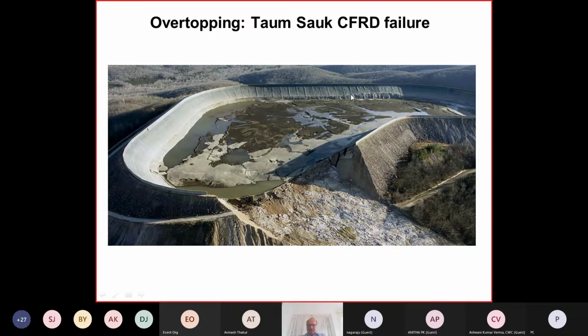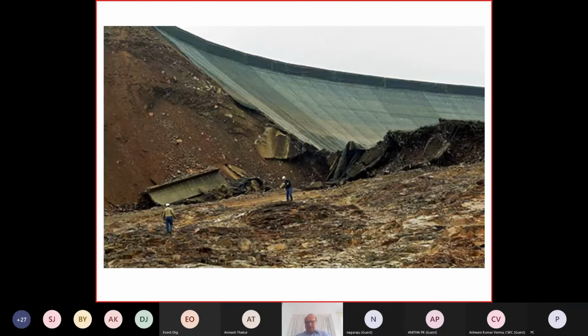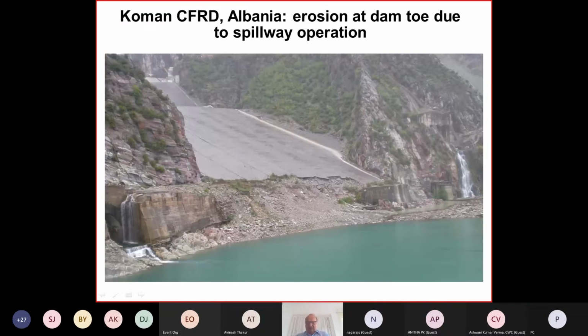So even if you are on top of a hill with no inflow, as part of pump storage, you must have a spillway. Okay, it is that simple. We see here some parts of its concrete face. The rockfill dam doesn't really look like what you would say rockfill, but from the compaction and so on, it looks more like earth.